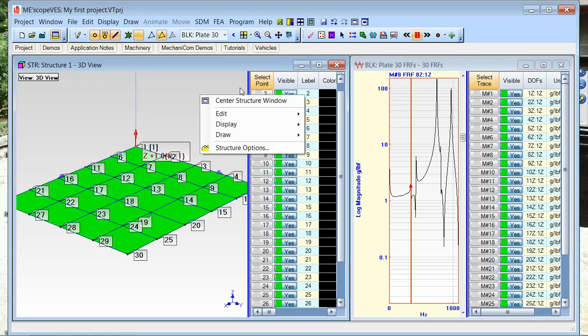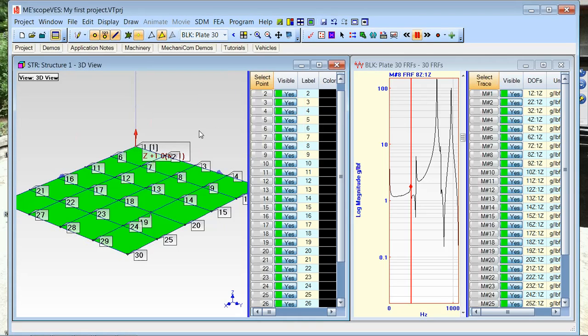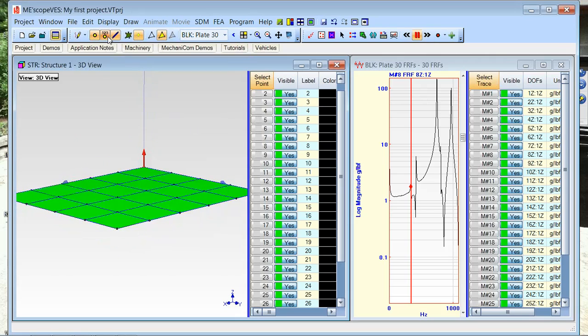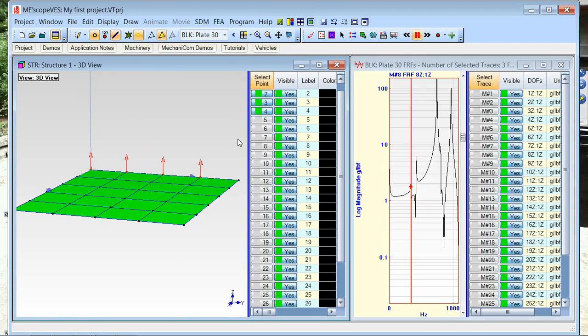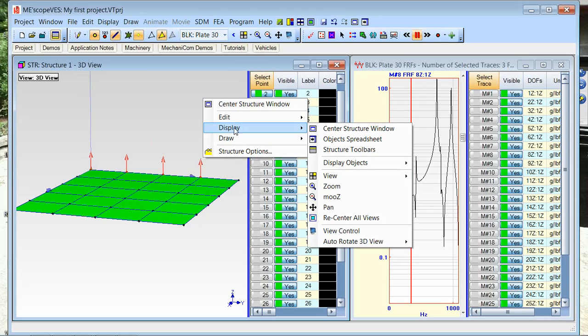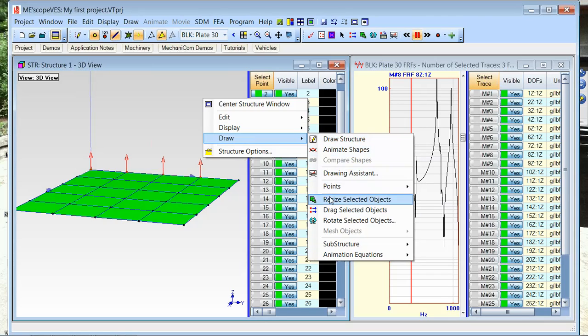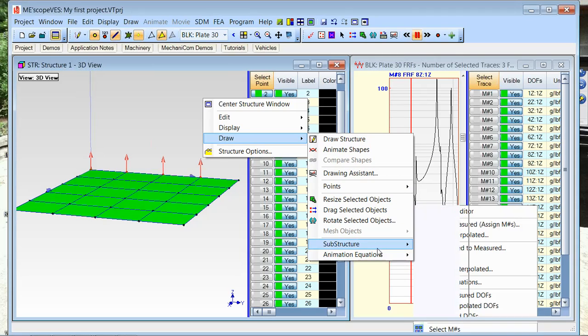Let me show you something else. I can use a different cursor here. I'll use a peak cursor, and this is very useful when I have data where the peaks are moving around. I'm going to turn the peak cursor on and put that over here. Now I'm animating from the peak value in each of my measurements. And as I scroll through here, you can see the little red dot. That's the data that's actually being used for animation. You can see down there, if it doesn't really find a peak, this is near a node point, it just picks the one in the middle. And that's not going to change my shape a whole lot.